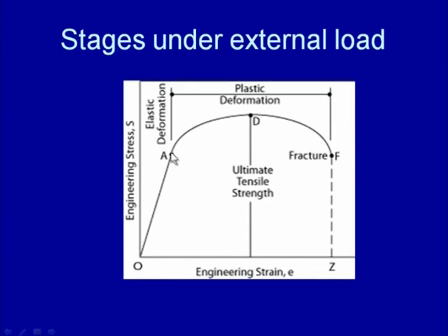So, when the loading is in this range, the first kind of deformation will be occurring, and when loading is in this band of the engineering stress diagram, then plastic deformation will be occurring, meaning failure due to plastic deformation will be taking place, and when the load goes further on the higher side, then fracture will lead to the failure of the weld joint.